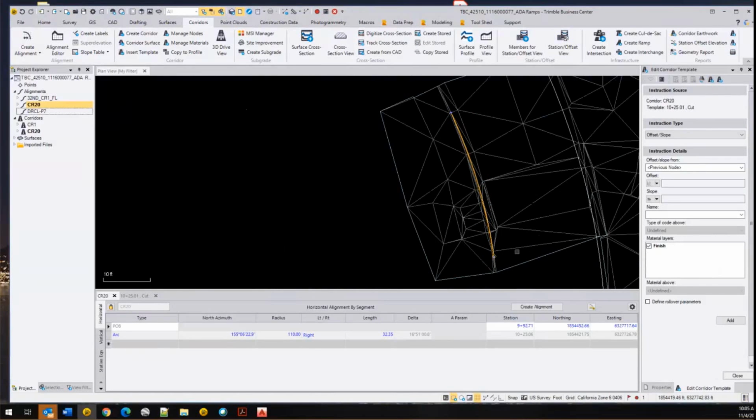It could be that he changed the radius of the curve and didn't update his table in the PDF. Mark, was that you? Would you repeat that, please? I'm thinking maybe the engineer rounded the radius of the curve differently. I guess you could still have the beginning and end point would be the same, but if you have a different radius, then the length of your curve, and then again, the length of your alignment would be different. Yeah, so I think for that radius, you would have to move that radius quite a bit to affect 600ths and change.